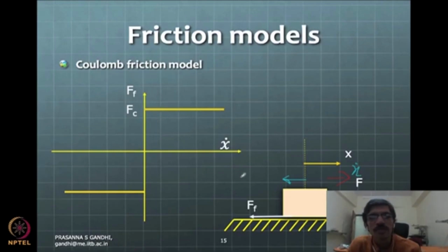So this mu n, you say, no matter what the velocity x dot is, your friction is always mu n. That's the maximum, limiting value of the friction that you consider. We don't consider any dependence on x dot for the friction in our normal Coulomb friction model, or what we have studied in mechanics, I mean the simple JE kind of classes. So write down this equation.